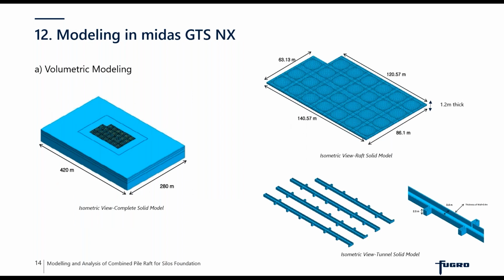Now we have various components. As we already know, it's a pile raft foundation, so we have a raft and piles, but we also had feeder tunnels beneath the raft foundation, and it was very important to model them to understand the interaction between the raft and the tunnel, and the pile and the tunnel, to have a complete picture of how exactly it is affecting the settlement of the whole foundation system. So we adopted a volumetric modeling for the raft. The raft was modeled as a solid element, and so was the tunnel.